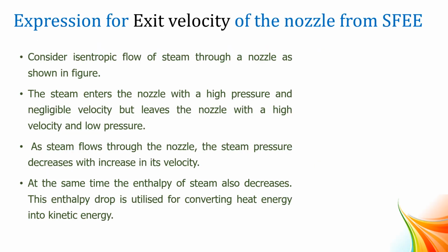So, the expression for exit velocity of the nozzle based on the steady flow energy equation. As we have come across steady flow energy equation for various thermodynamic components like boilers, nozzles, turbines, compressor, condenser. For nozzle also we have a steady flow energy equation. There we will be coming across kinetic energy alone. There will not be any heat energy. So we will be having kinetic energy, no potential energy, in the case of nozzles.